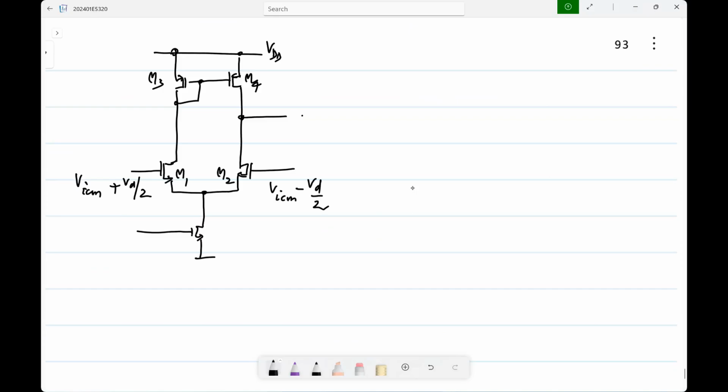What is the value of VD at which one of the transistors, input transistors, will cut off? Going by gm. Okay. Is that correct? What is the value of VD at which one of the transistors will cut off? Or does it depend on VICM? How will you find out? I mean, yes, the 2I0 by gm is assuming a linear behavior for gm, right?